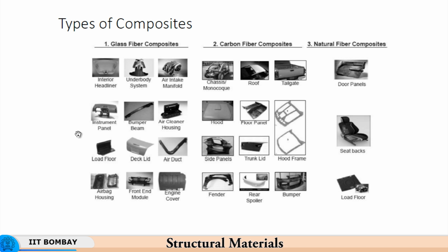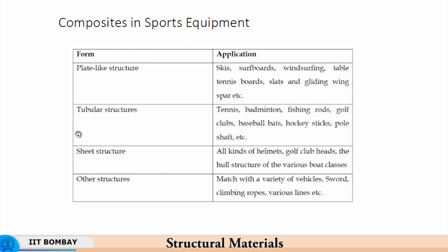But if you look at the energy required for this, these artificial materials are all energy intensive. So at the end of the day, you have to spend a lot of energy. Although you might save a lot of energy in use, because the product became light, you need less fuel, particularly in the transportation sector. So you might say that emissions are reduced, but then overall, to make these composites, a significant amount of energy is required. So from that point of view, they are not all that green. But then yes, if you look at the strength to weight ratio, the enhancement of properties is significant.